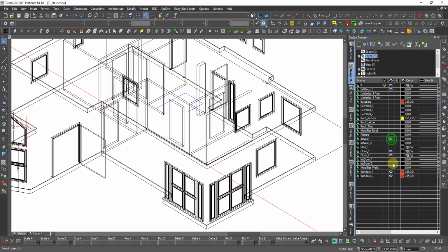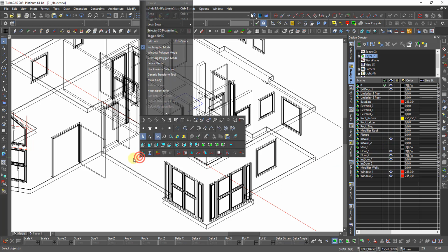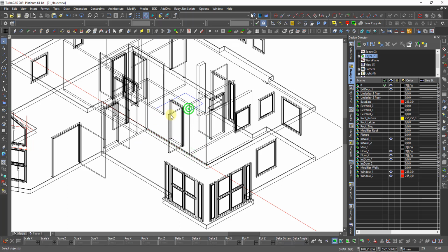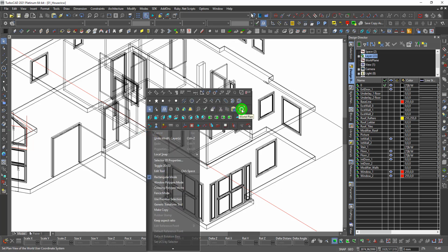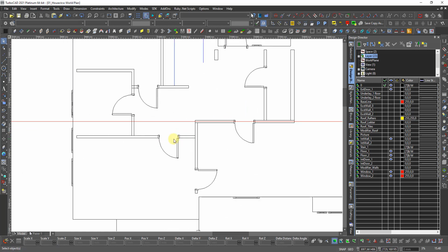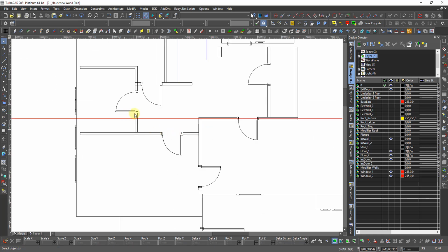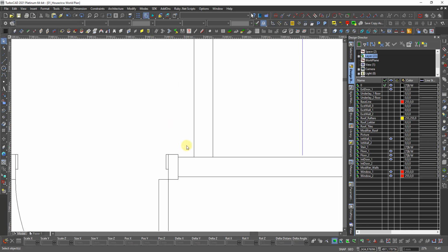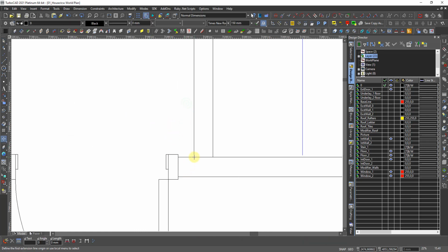Then I need the wall and I want the door on the first floor. I set workplane by entity. You select one door, I can take the wall, doesn't matter. I see it from the top, and then we want to know this. I remember we set 65. This one we have not adjusted. So then we have two ways. We can take the measurement, V to V, then it's 82.